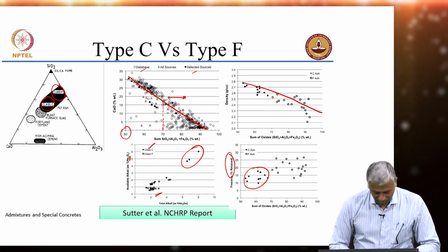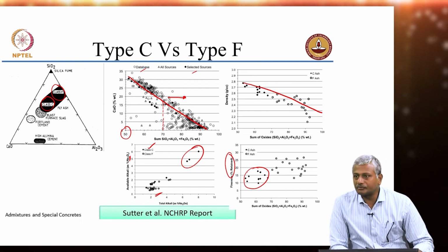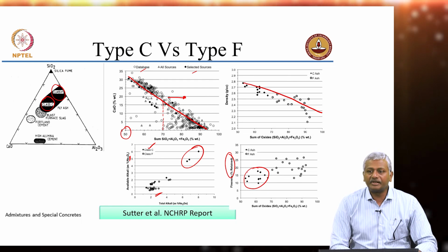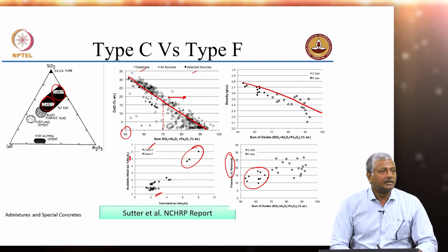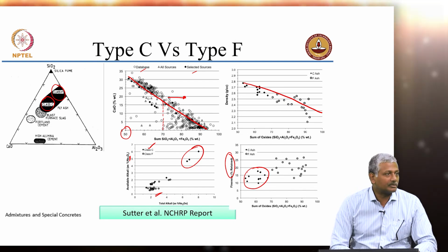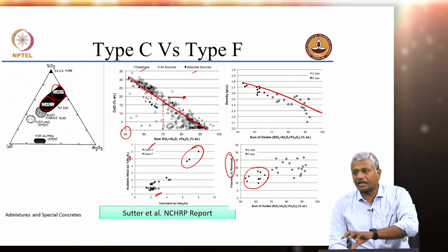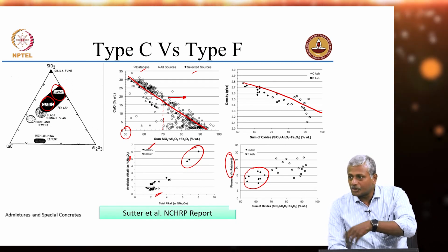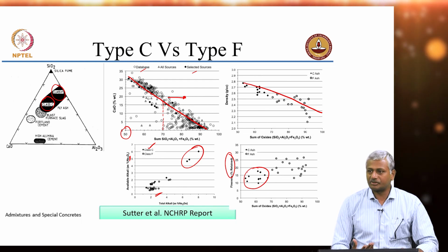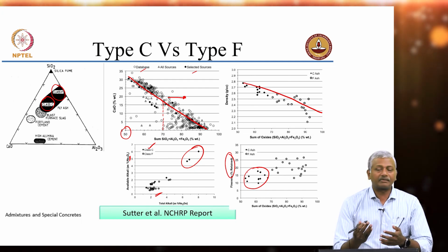Now, interestingly, the conditions are not that easy to predict. For instance, if you go to Ennur thermal power plant north of Chennai, they sometimes get fly ashes from multiple sources, right. They get coal from the coal fields in the Bihar, Jharkhand region, or they can also get coal from Indonesia, okay, depending on what works out best for them economically. Interestingly, it turns out the coal that we get from our Bihar, Jharkhand region seems to produce type F fly ash, but when they get coal from Indonesia, it changes the entire characteristic because it is a high calcium fly ash, and it also has a different color, right. So, when the source of coal changes in a thermal power plant, the fly ash characteristics may change significantly.